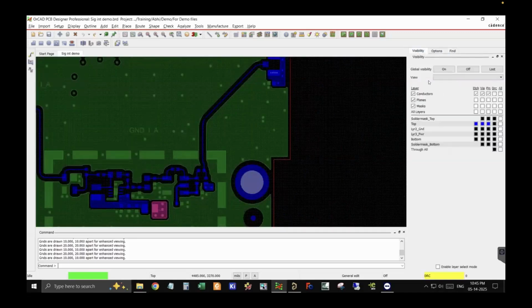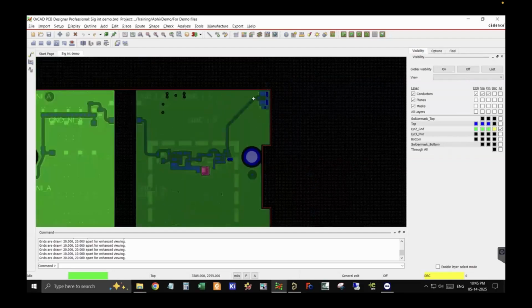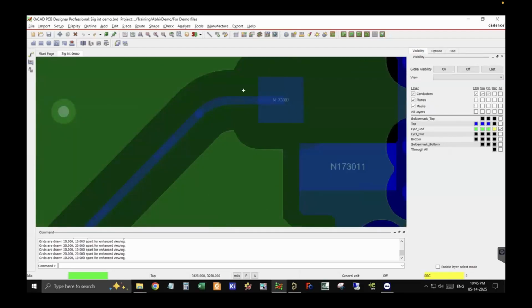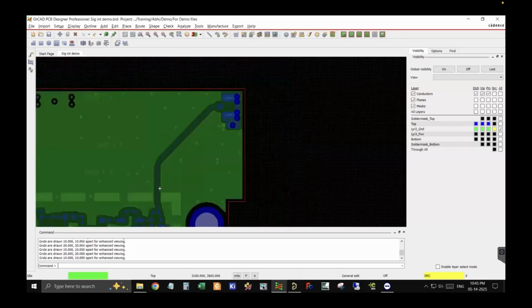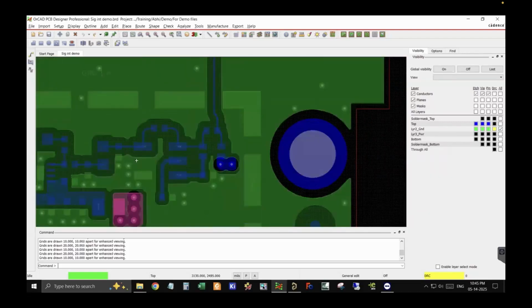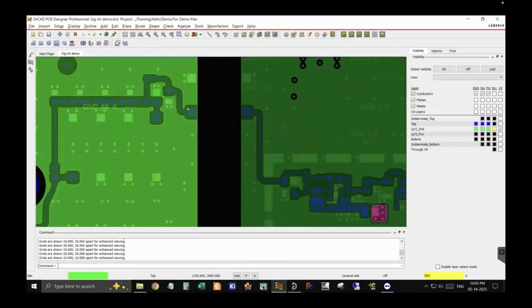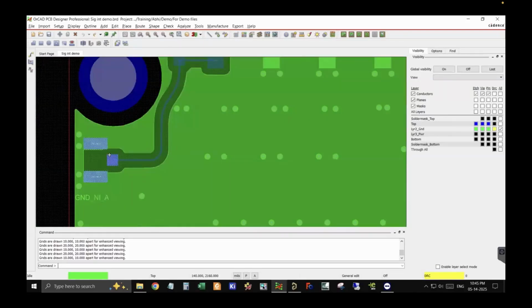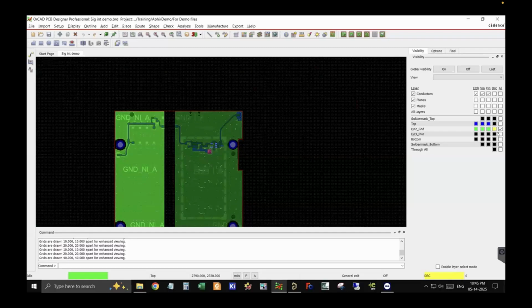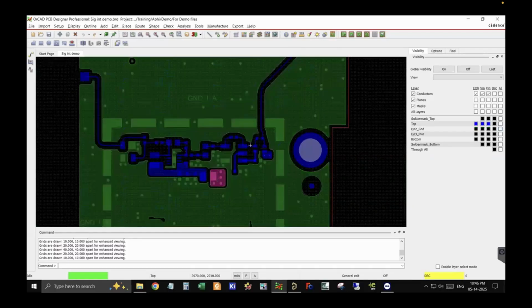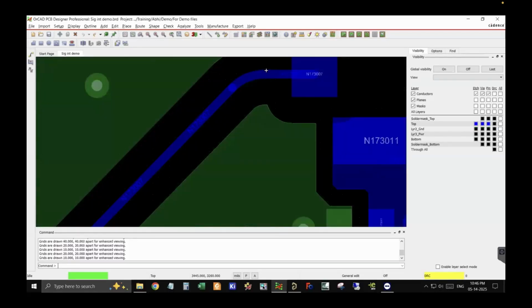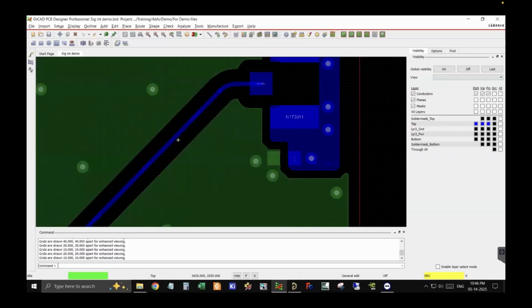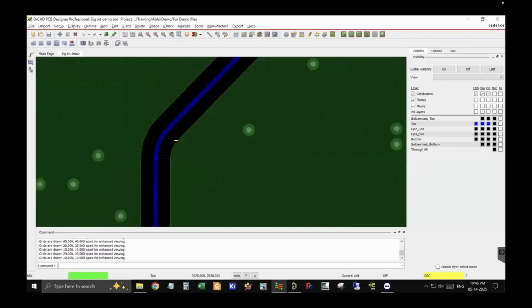So the next thing is the reference plane. Now your signal line should have complete reference planes on your adjacent layer, which is layer 2 in our case. As you can see, we have followed complete reference plane. There shouldn't be any splits in your reference planes anywhere. So make sure that all the signals have complete reference plane. Now we have also used curved angles over here. Curved angles are better in case of impedance lines generally, because 135-degree bends can create a small impedance discontinuity.